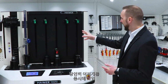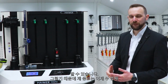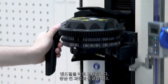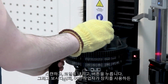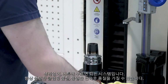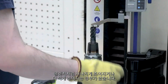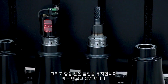Now, as this is a station with many cooling positions, we can of course do simultaneous work. Therefore, my colleague now goes on changing the second end mill, and it's the same procedure like before: scanning, moving down, pushing the button. And you see also, no matter which operator is using the machine, it's a push button system, always the same quality in clamping, the same quality in run out, not like with a collet chuck where you're over tightening, under tightening. It's always the same quality, very fast, very clean.